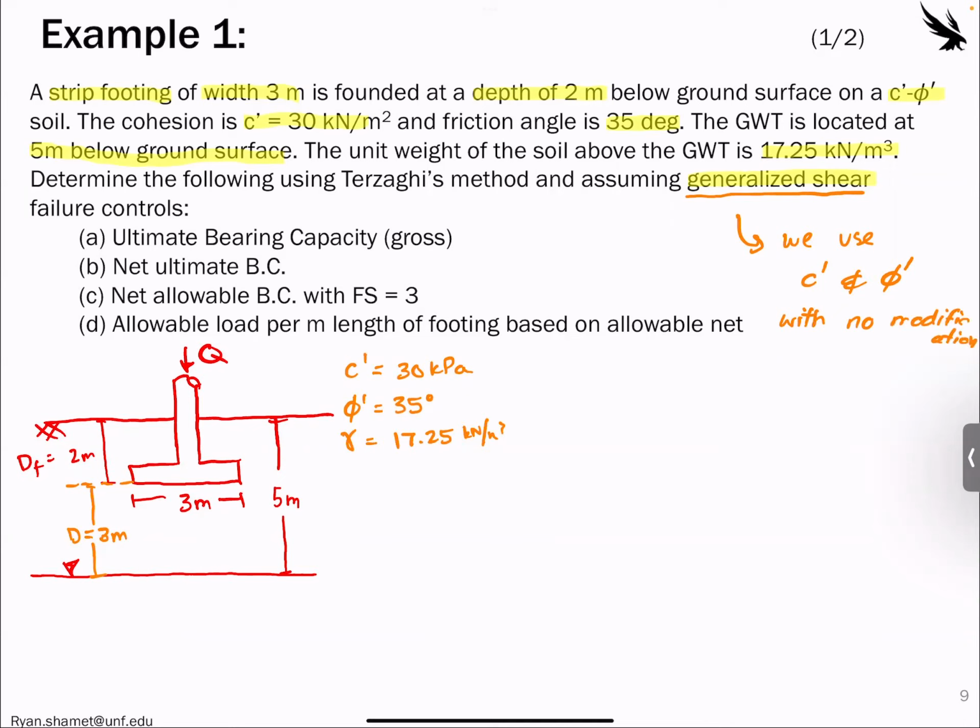The next thing we would look to do is find the Terzaghi bearing factors, or N factors, based off of this. So we would then look up Terzaghi's bearing capacity factors. And from this class, that is on last lecture, so lecture 15, slide 13.